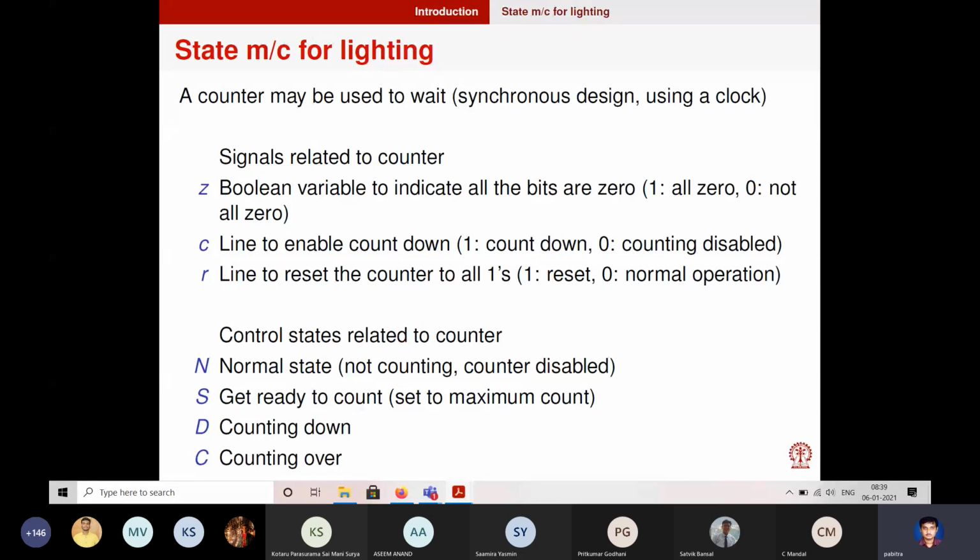What we bothered is that we can decouple this. So your counter will change state only at these time instances. It's synchronous with this clock. Whenever the clock changes, only then you can do something. So this has its advantages. You can naturally see that all these problems of what will happen in between are no longer there. Everything happens at the clock. Any change happens only when the clock ticks. Okay, and is this clear?